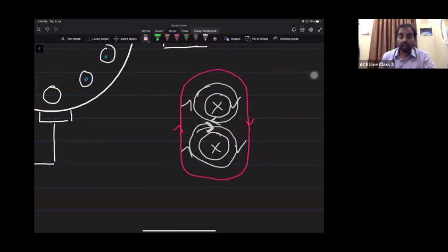You have to draw a straight line. Is it clear? So can I say if two conductors are carrying currents in the same direction, and if the magnitudes of the currents are the same, then there will not be any flux lines passing between those two conductors? Why? Because the flux lines between those two conductors will get cancelled out. So there will not be any flux line.